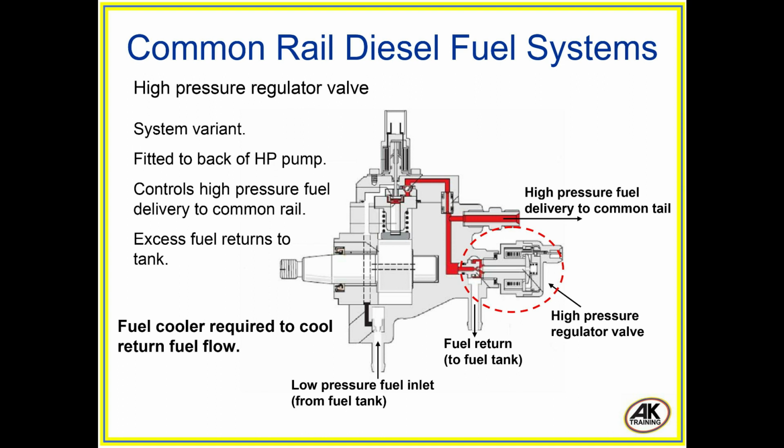High pressure regulator valve. System variant. Fitted to the back of the HP pump. Controls high pressure fuel delivery to the common rail. Excess fuel returns to the tank.